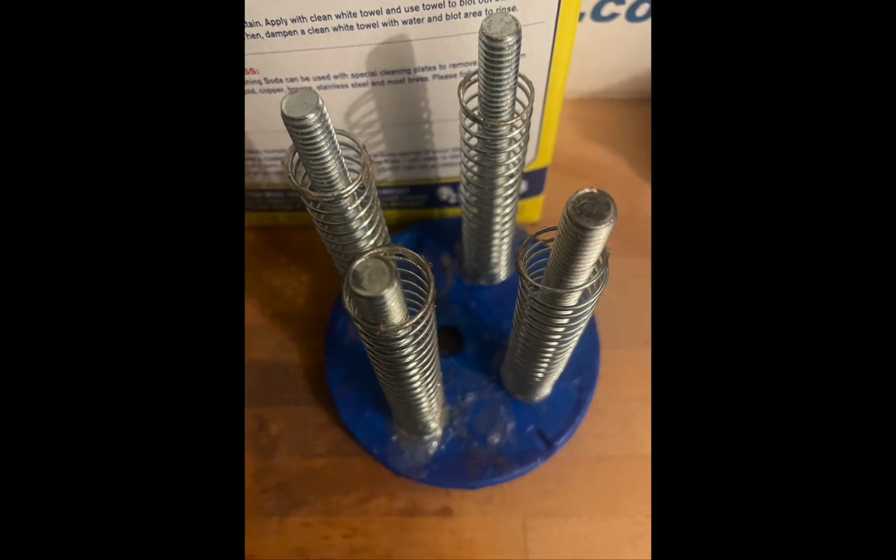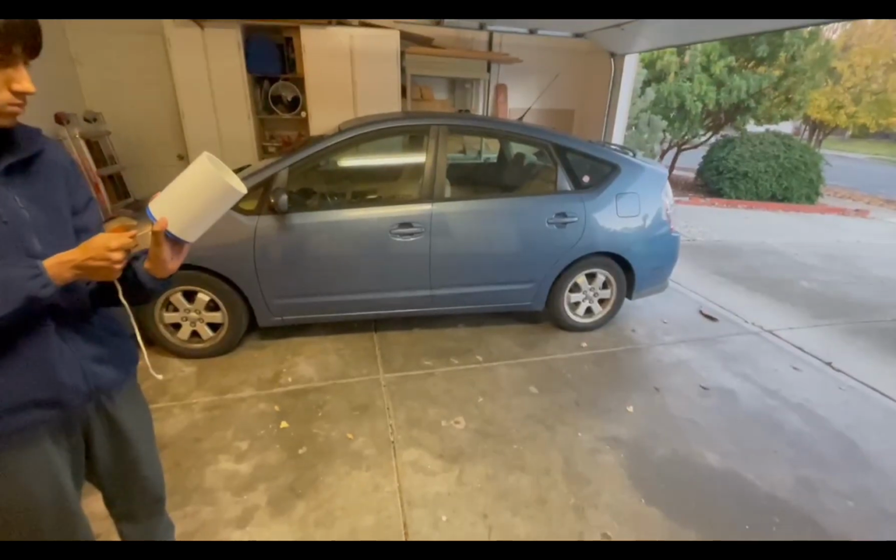To restrict the springs from rotating, we decided to place them around steel bolts. We drilled 4 holes for the springs and secured 4 bolts with the nuts. This allowed for the spring to compress completely without rotating with one another. We also drilled 4 holes in the upper disc and used nuts on the top to secure the disc from falling off. This allowed the disc system to snap back fully due to the springs being able to fully compress.